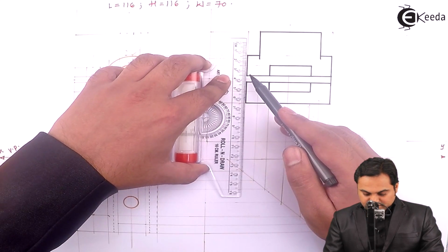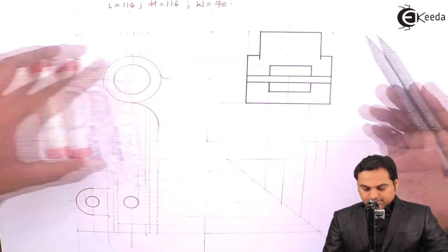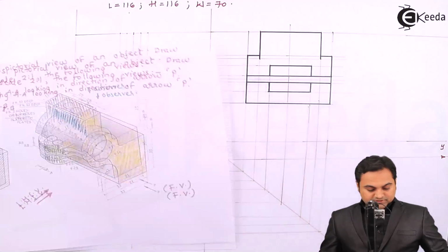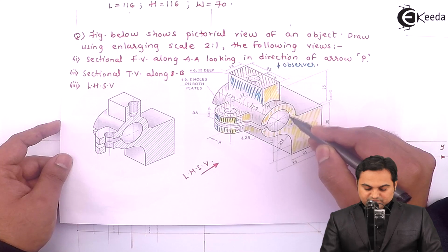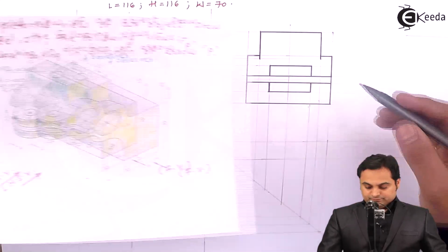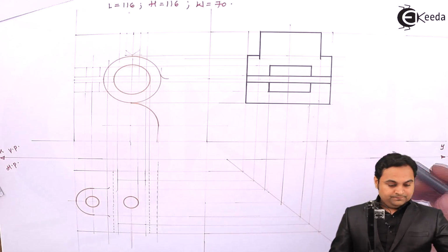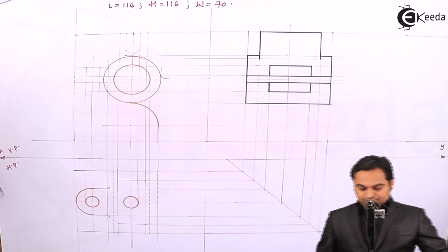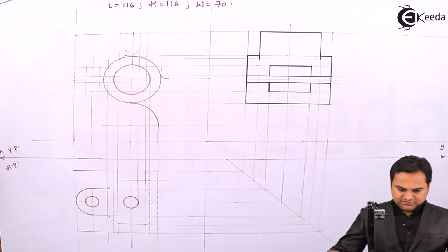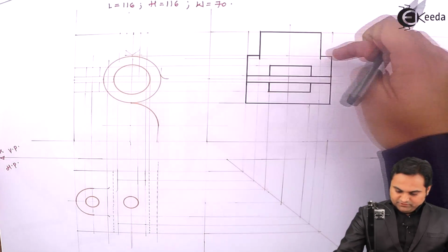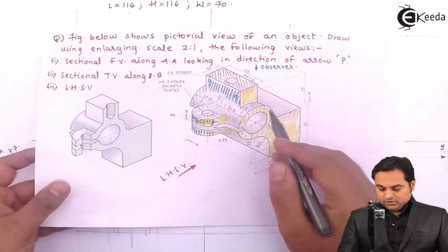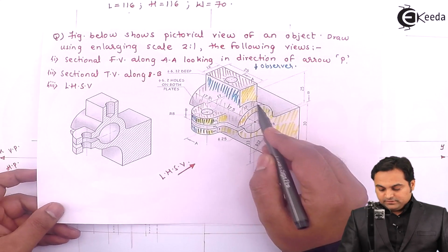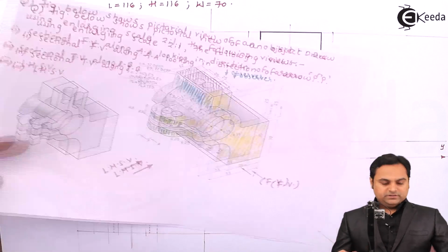Here there will be this dark line because from this gap, here this circular surface will be visible as a line, so that line I have drawn. Then the part of the cylinder which goes inside this rectangular surface will be hidden, because this cylindrical surface is there throughout the width.